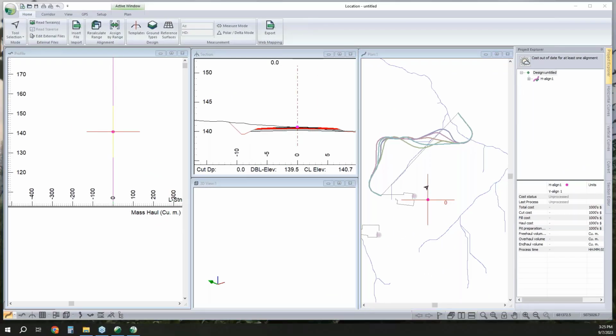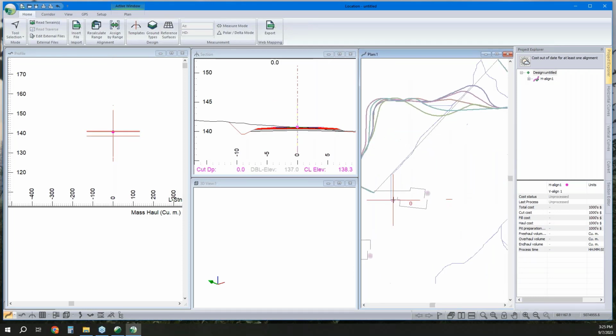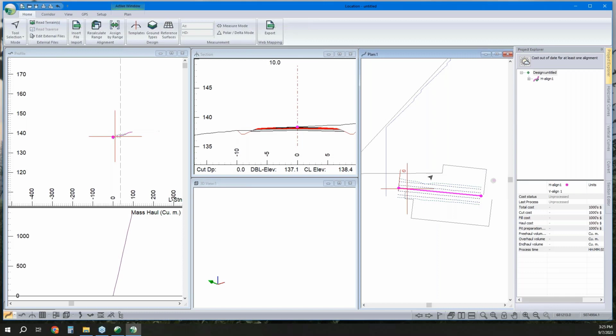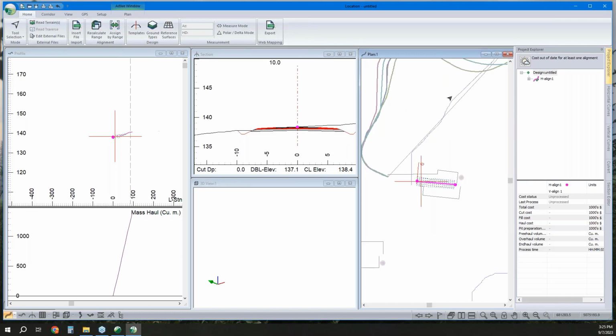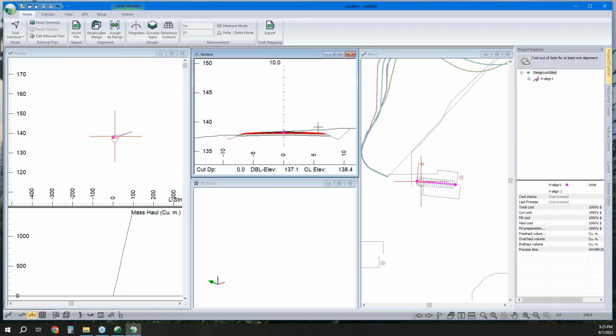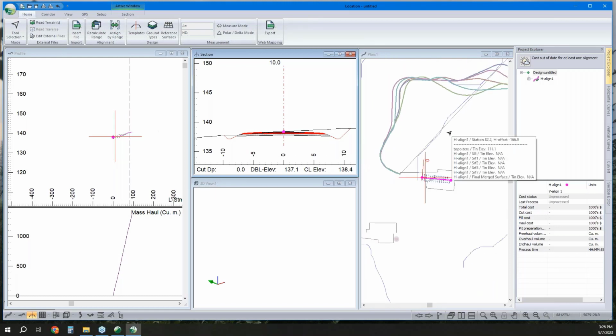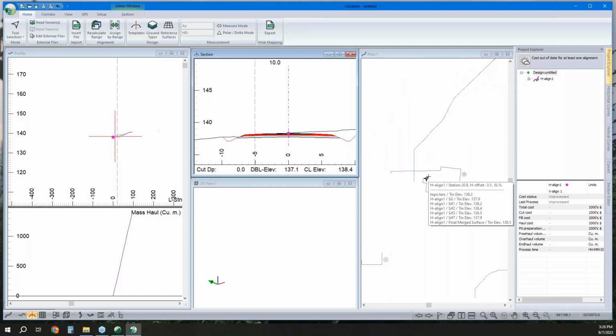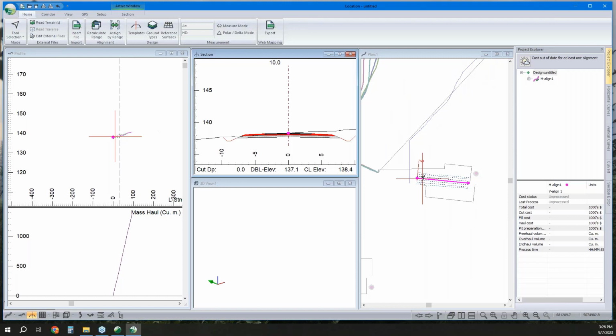All right. So I'm going to just move this starting point here, and we'll worry about our alignment later, but I'm just setting it within the confines of this proposed pad location. To start, my cross-section geometry is the default civil cross-section geometry when you install the software. In this project, I want it to be a gravel road. So this kind of rural highway cross-section geometry isn't super appropriate. So I'm going to change that. And then, as Aaron said, I'm going to include the geometry of our pads in our cross-section geometry here.